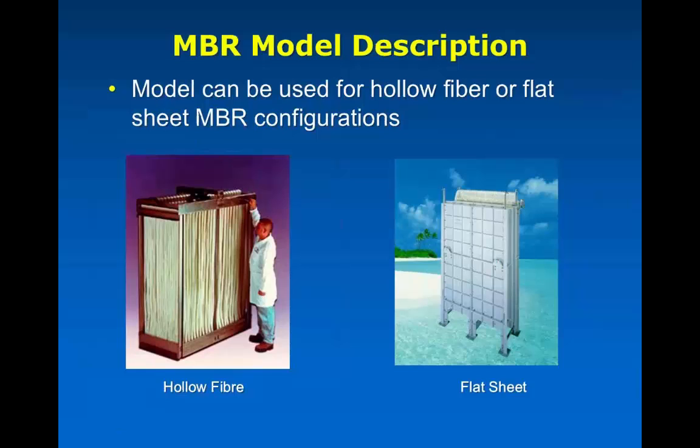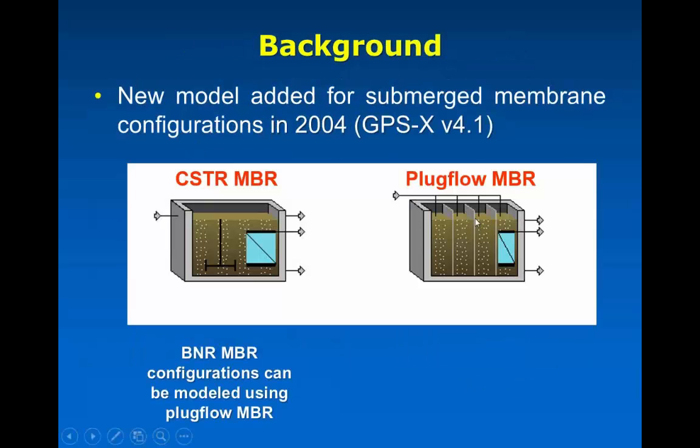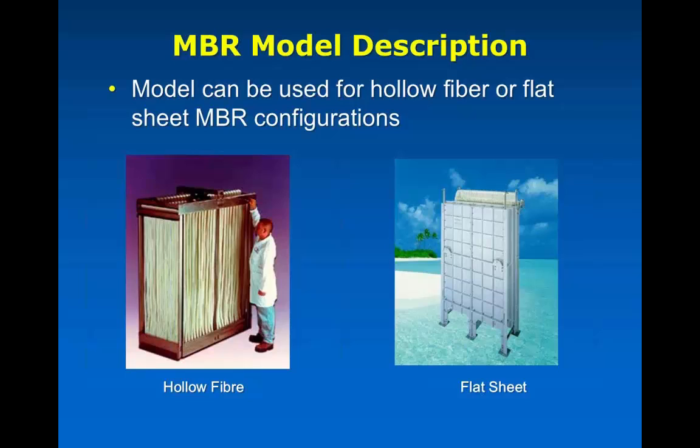So first of all, I'll mention that our MBR model is there and it's doing solid separation, and we're doing the formation of the solids on the surface of the membrane, forming the cake. And that formation of the cake and the way that the flow moves through the membrane is assumed to be the same no matter what the configuration of the surface is.